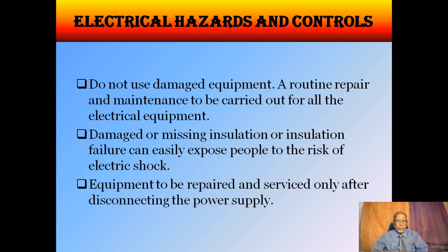Equipment is to be repaired and serviced only after disconnecting the power supply. See, when somebody reports to you that this equipment is showing some error, when you want to repair that equipment, it should be disconnected from the power supply. Then only you should carry out the repairs.